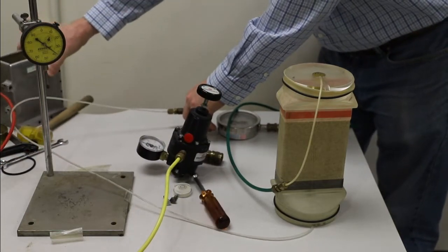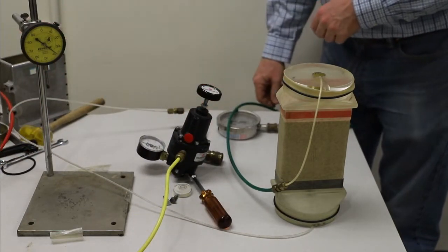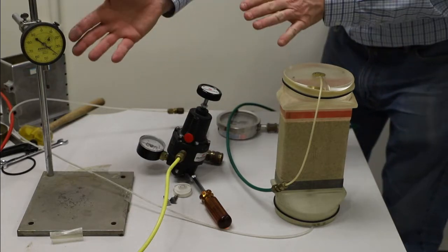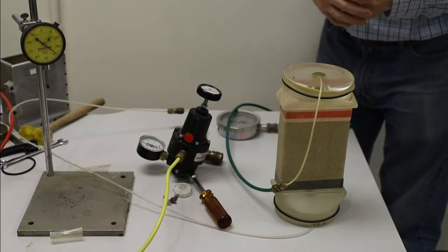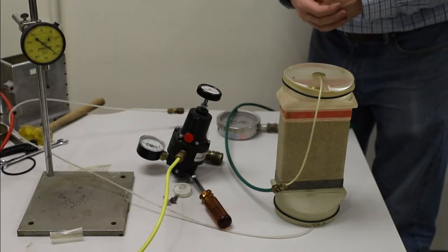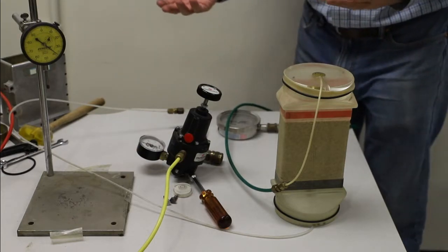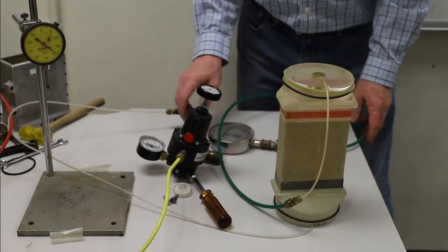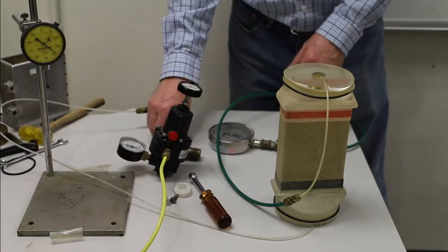The height measurement is exactly like we did with the triaxial specimen. We're going to put the whole system underneath the dial gauge and look at the difference, or the change in height, relative to when we had a known reference between the two caps, so that's pretty straightforward.